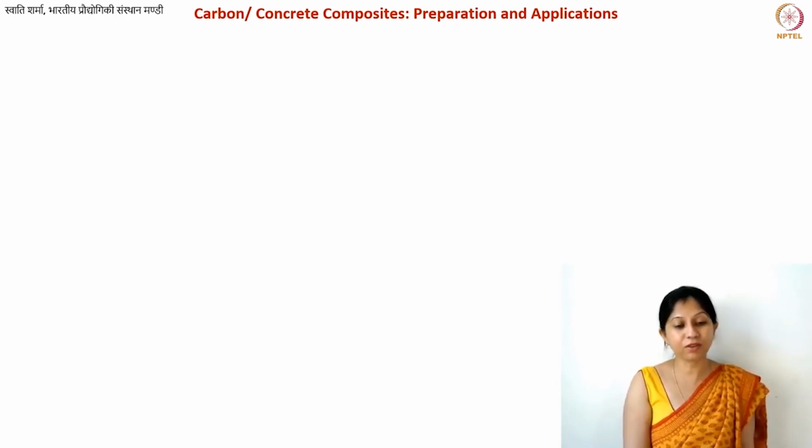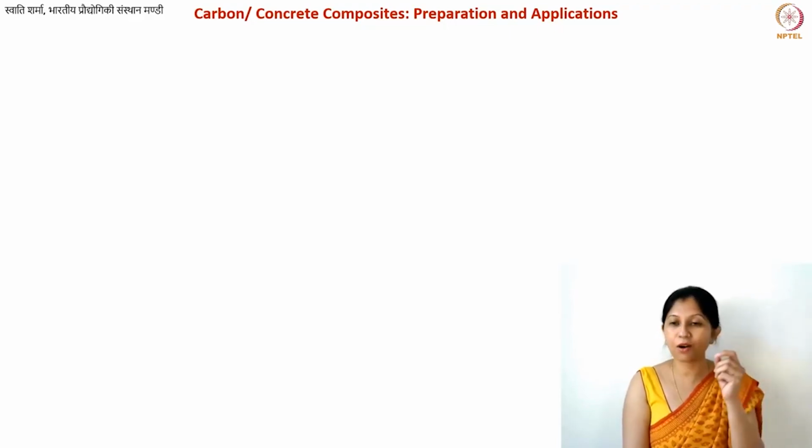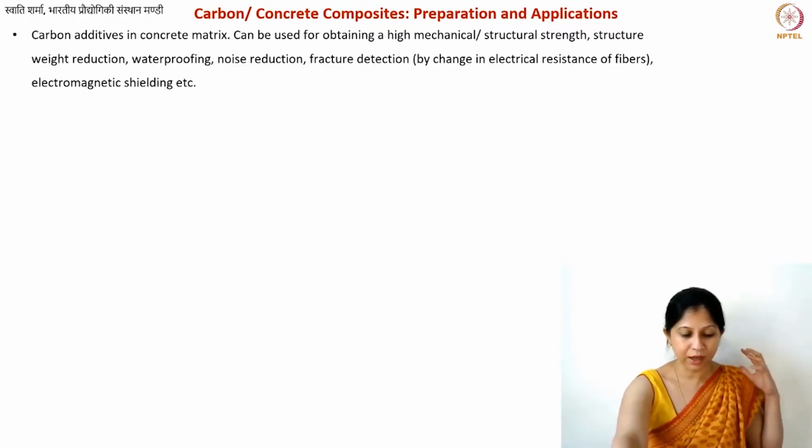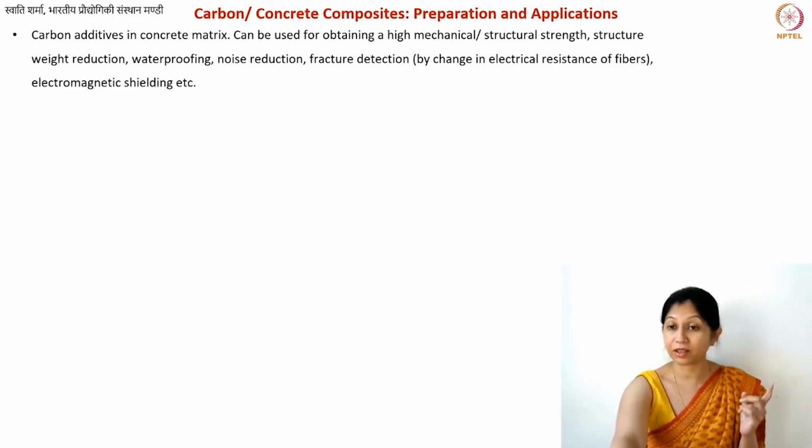However, sometimes you just want to make your concrete stronger. And for that, what you need is filling of the pores of the concrete. That can be done using carbon nanomaterials. So in this case, we are also using carbon particles, although very small, nanoscale particles, or graphene, or even carbon nanotubes. For reinforcement of concrete, you can use carbon nanomaterials. However, fibers still happen to be the first choice for giving the structural strength.